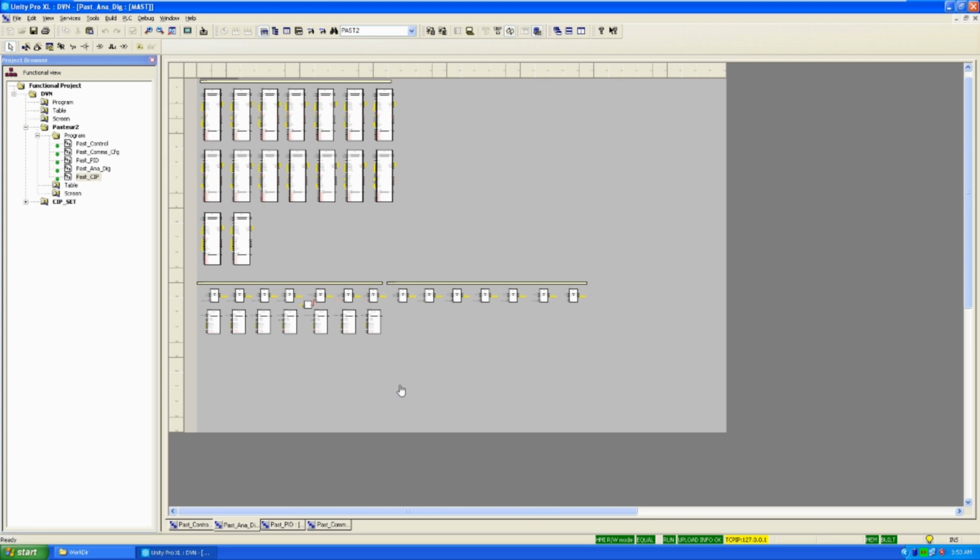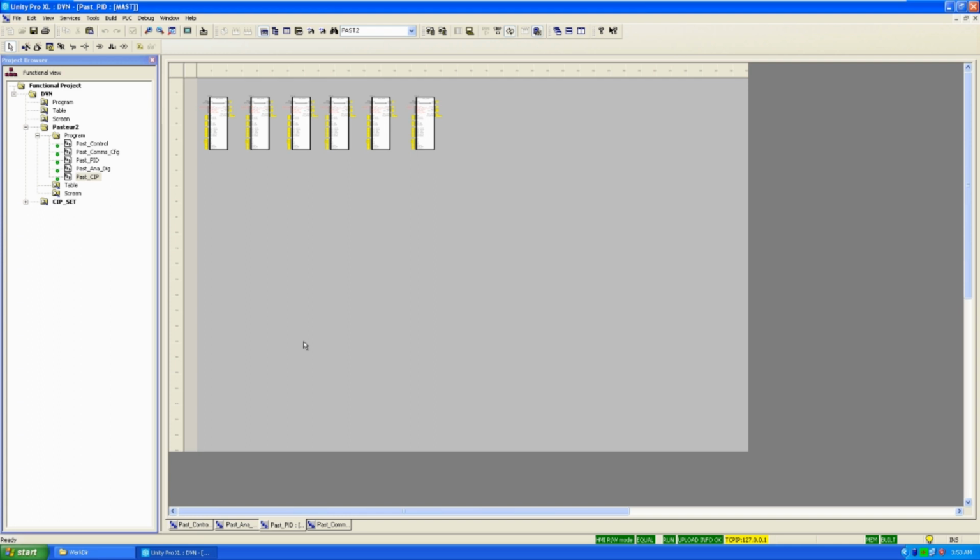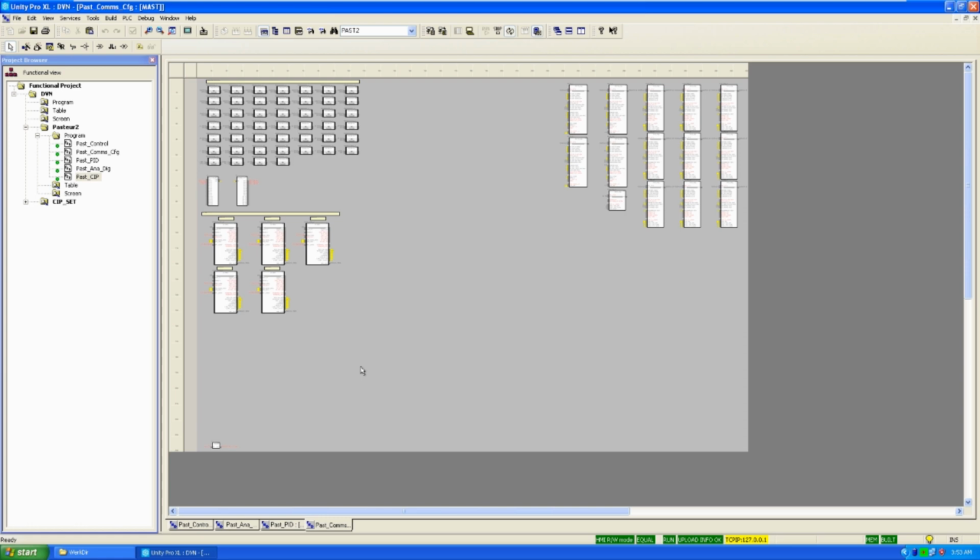All the function blocks that are shown here are generic, so they're standard. We have the PID loops, which are 6. Again, these are standard blocks. Approximately 15% of the sheet is occupied. We have the communication with the field and the configuration. The configuration is shown left here. Whatever was available on the faceplate can be hard-coded by using a function block here.